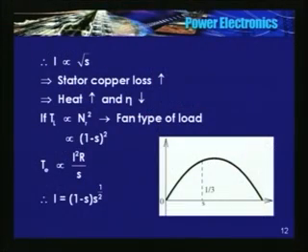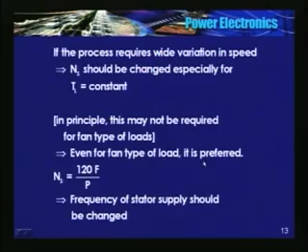So here it is. Stator current attains a peak at S equal to 1/3 and again it comes down. So in principle, you can vary the speed of a fan type of load by varying the applied voltage to the motor, keeping the frequency of the stator supply constant.